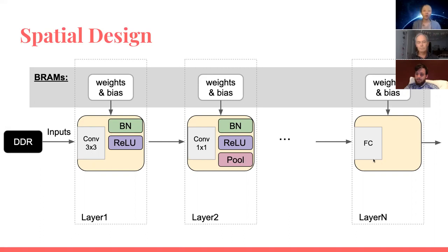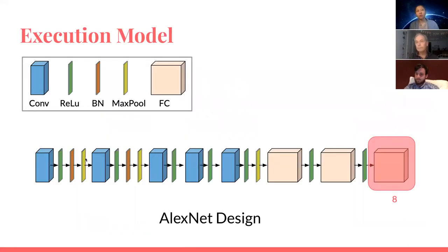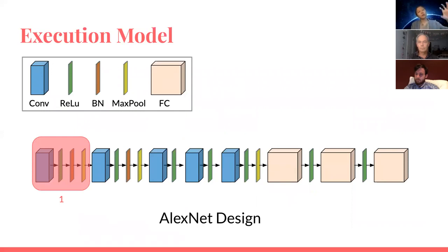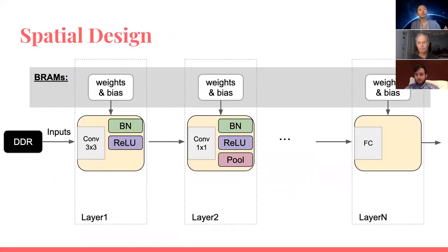So that means that we're trying to compute different layers at the same time. If you think about the processor design, it's like we will have instructions at each stage of this processor. So this is what we meant by spatial design. That means that instead of turning the computes into the time dimension like this design, where for each step we map the whole hardware to one step, we map more of the time dimension onto the spatial dimension, meaning that we perform more time steps in the hardware at a time.